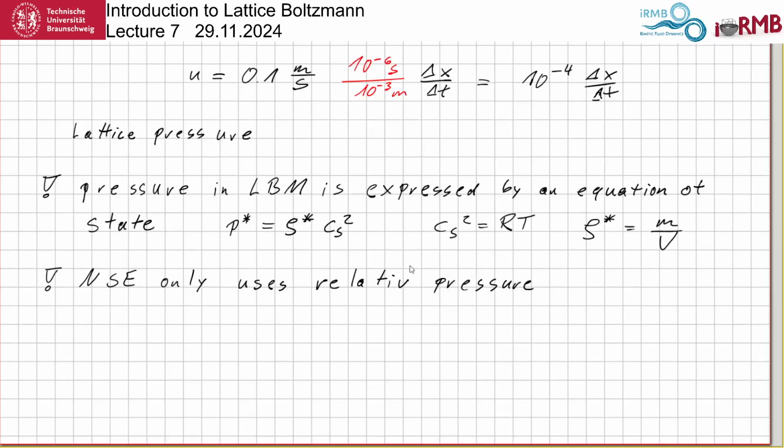Okay, so what are we doing? We have a fixed temperature, so what we are doing is we say that we take a relation between the pressure and some zero pressure, normal pressure, I don't know, and relate this, so their ratio is equal to the density in lattice Boltzmann and the reference density. Yes? This equation for the pressure in terms of the density comes from the ideal gas. This is the ideal gas equation.